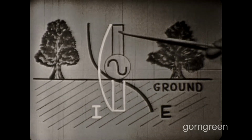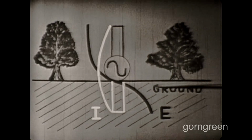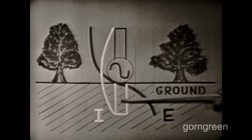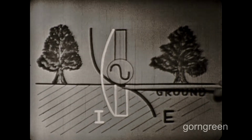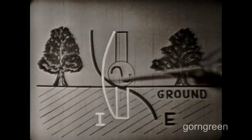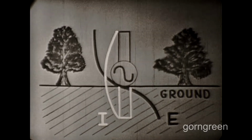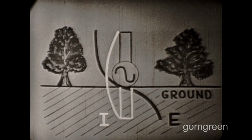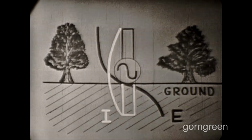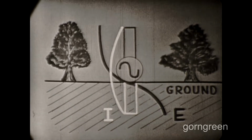This is the radiating element. This, of course, is the ground. And this is what is known as the image. If we had X-ray vision and could see the current and voltage wave shapes below the ground, the entire pattern would look exactly like the half-wave dipole or Hertz antenna. Since Marconi's theory was responsible for the development of this quarter wave antenna, it is called the Marconi antenna.